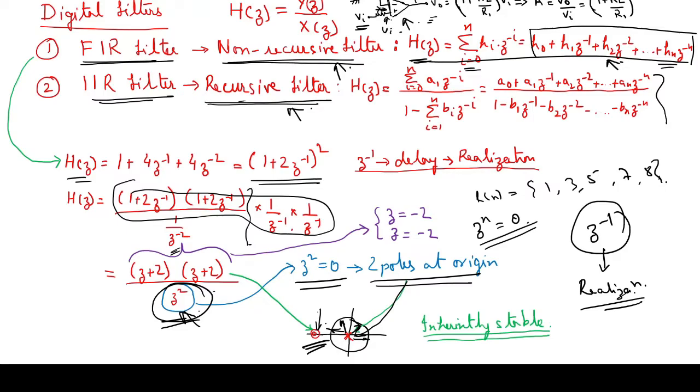Yes, not more stable. FIR filters will be inherently stable. वो हमेशा stable ही रहेगा because all the poles they are within the unit circle. There is no way that you can place it anywhere else. So FIR filters they are inherently stable filters because of this reason, because all the poles they are present at origin. वो वहां से वो move ही नहीं कर सकता. Okay. So that's why see मैंने यहाँ पे लिख के भी दिखाया, they are inherently stable, right?